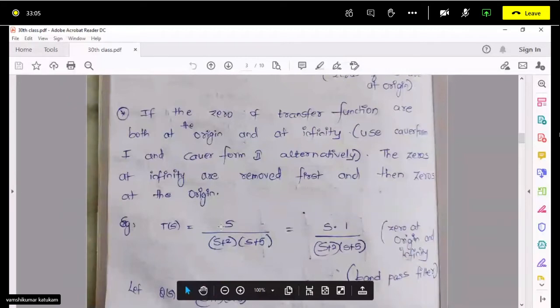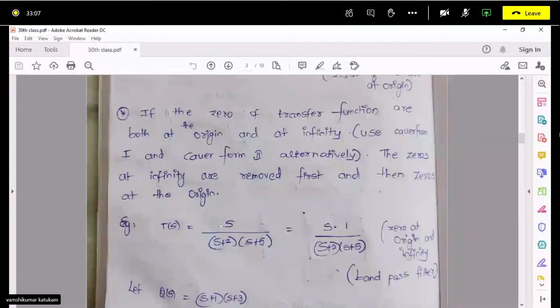So here just three forms to remember, if you have a constant in the numerator. Because in an RC ladder we have only negative real poles, we cannot talk about imaginary poles. Poles or zeros are negative real values. So in the denominator you have negative real poles.